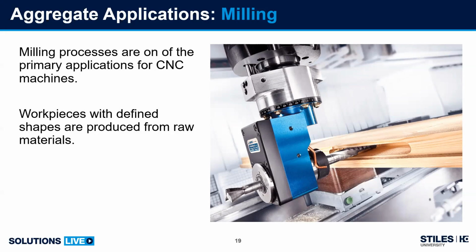We have a number of manufacturers that now have the capability to transfer air through the spindle down to the aggregate itself. So what that unit is right there is actually an air blow-off device. A great tool if you're making some of these deep cuts on these lock recesses, you understand very well that chips and things like that accumulate and can slow you down, reduce the tool life, dull your blades, etc. So this is a great way to minimize those effects.